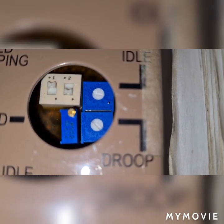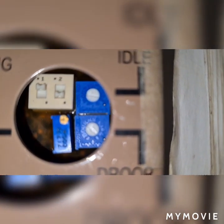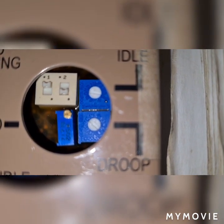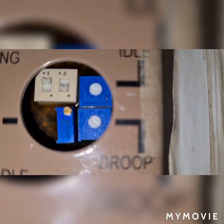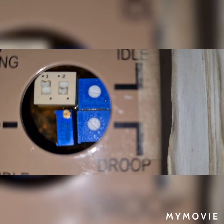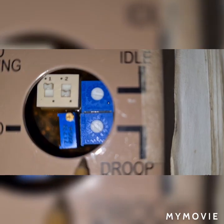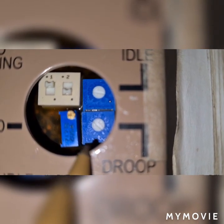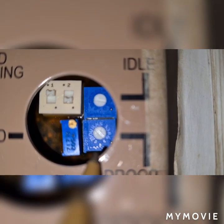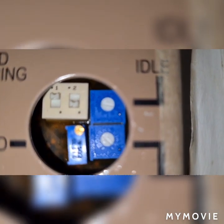Droop has to do with your generator engine in parallel operation, okay? So normally when you do a parallel operation of your generator inside the main switchboard control or engine control room, we have a switch there from which you can increase or decrease the RPM of your generator, or reduce the load on your generator, or increase the frequency of your generator from 60 Hz to 60.1, 60.2, 60.3 Hz before you switch on or put it in parallel with another running generator.